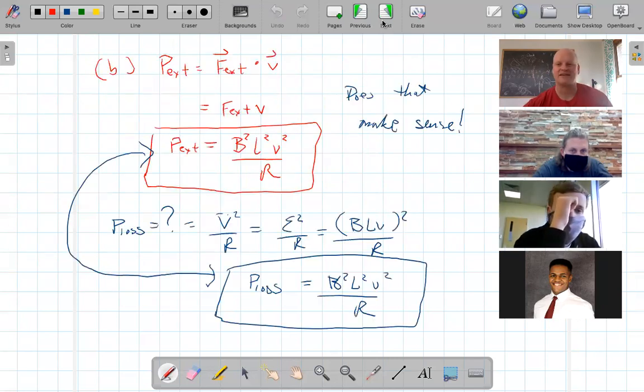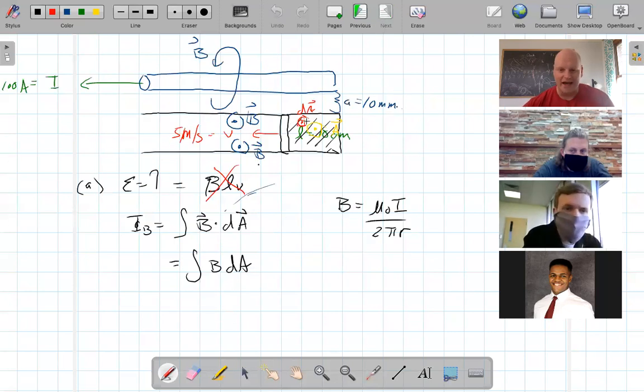So let's just kind of set up this integral and we'll go from there. So good. So dA is going to be then, so basically again, here is my dA. So dA is a small section in this direction, but this direction is what? The radial direction, which means dA in this direction is simply dr, and dA in this direction, I'm going to go ahead and call going this way the x direction. So that means dA in this direction is going to be dx.